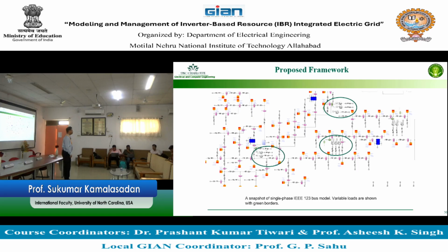What is a volt-VAR control? You are looking at a voltage and then finding out what will be the VAR requirement for that voltage based on a relationship, based on a graph. So that is the volt-VAR control. So that's linked. And volt-VAR-watt control. So we talked about that. We also talked about how we implement the controller in the field. We implement the controller as a primary control, secondary control, and tertiary control. Right? The difference between primary, secondary, and tertiary control is the